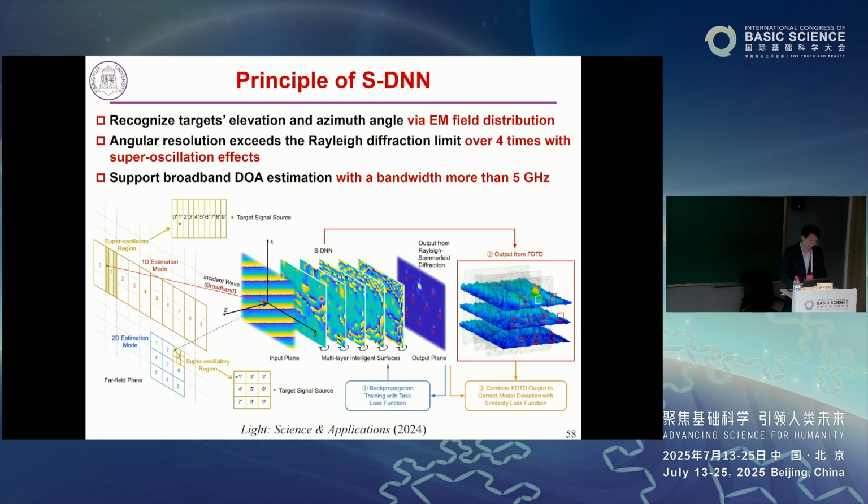So here's the full architecture of the proposed diffractive optical communications. The image on the top depicts the diffractive neural network encoders, diffractive electronic neural network encoders, and diffractive neural network optical decoders, which are jointly trained to transmit optical information around fully opaque occlusions. For each input message, such as an image, the encoders generate the phase modulation patterns, which are then applied to modulate planar waves at the transmitter side.